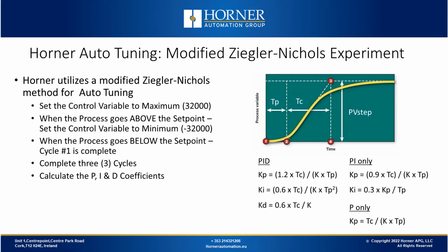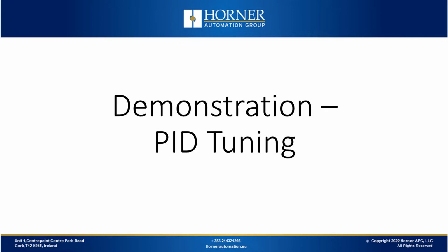When it gets below the set point, then one cycle is complete. The OCS continues that process for 3 complete cycles, and based on those experiments, it calculates the P, I, and D coefficients. Now let's begin our demonstration on PID tuning.